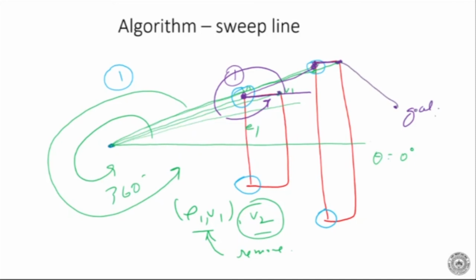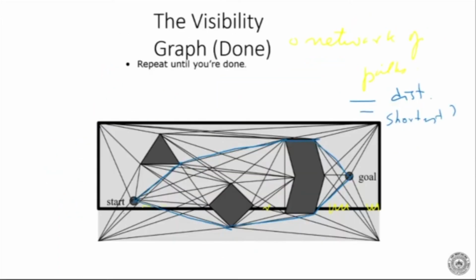Okay. So this is basically giving us the sweep line algorithm, which basically tells us what are the various interconnections between the nodes. Okay, and that is giving my roadmap. So in the previous examples, we said that how to get the roadmap. This is how we can get the roadmap. Basically, we can shine a ray of light and see where it is hitting and identify these vertices. Okay, then this is actually like a ray of light, so it's hitting that, it's hitting that, it's hitting this. So that is like a road in the roadmap. Okay, and we are making the connections to all of them.